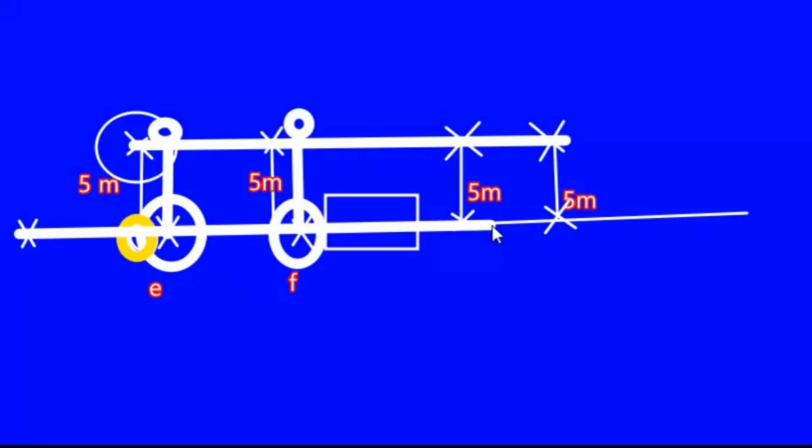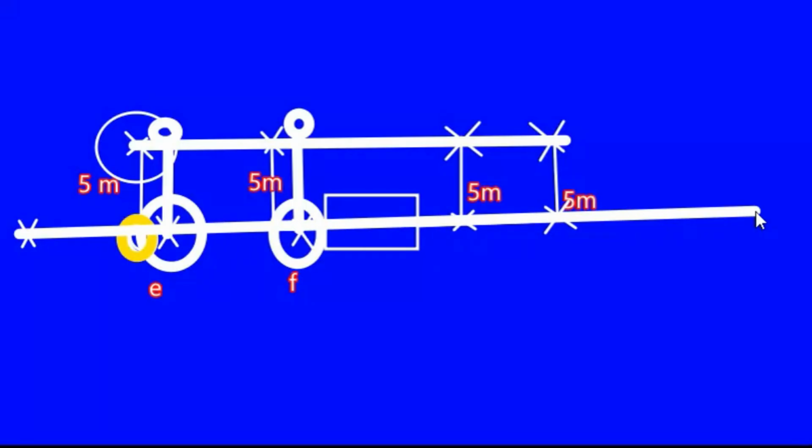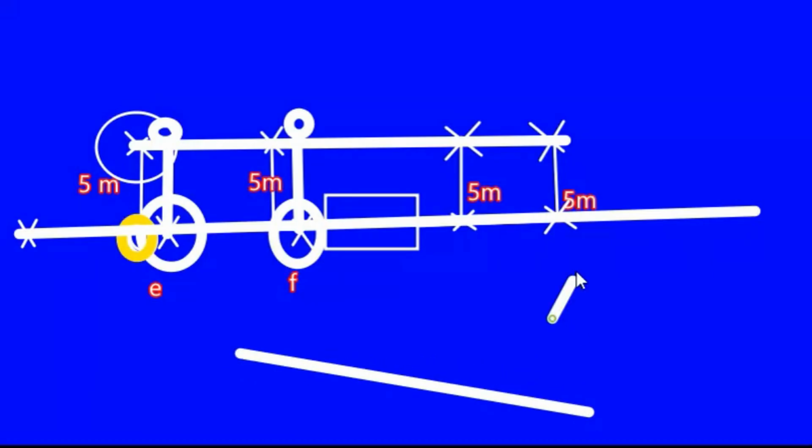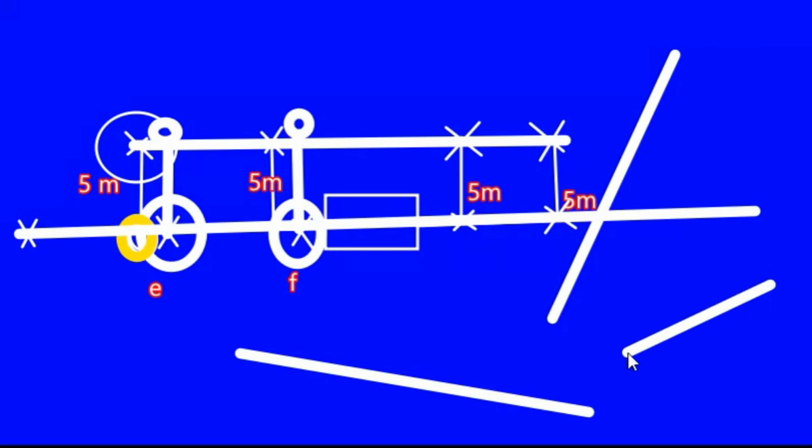A straight line is any line that can be drawn either way. I'll just give you a brief explanation. Like this is a straight line, this is a straight line, this is a straight line. So these are all straight lines. So don't get confused. The ranging does not have to be absolutely parallel to the building. Your ranging has to be absolutely in line. So this is the second way of doing the ranging when your ranging and chaining both are obstructed.